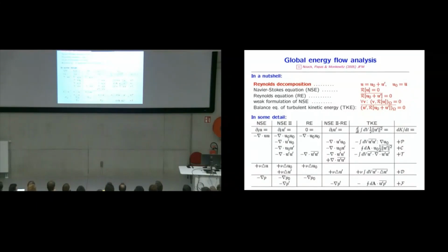Now we go one step further. What can we do having this fluctuation? We can get a lot of inspiration when we look at Monin-Yaglom. All the equations which you see there, where you have the flow decomposed into a mean flow and a fluctuation, can be written much more accurately in terms of a POD mode basis. So we start now with the Reynolds decomposition. I will remind you of an equation which you should know from fluid mechanics. The Navier-Stokes equation is written like this.